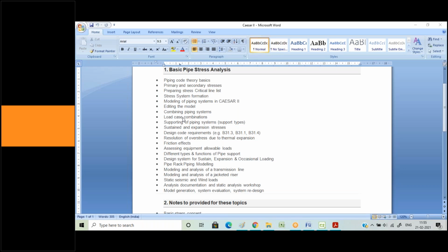By lock pin, basically I'll explain to you, because springs have a lock pin. When they come to the site, they are placed below the line. The pipe is resting on it, but the pipe is not in operation. Say the pipe has just been installed, and the stress engineer has recommended that there has to be a spring at this particular span from any number of points, whether it's from an elbow or some nearby support.